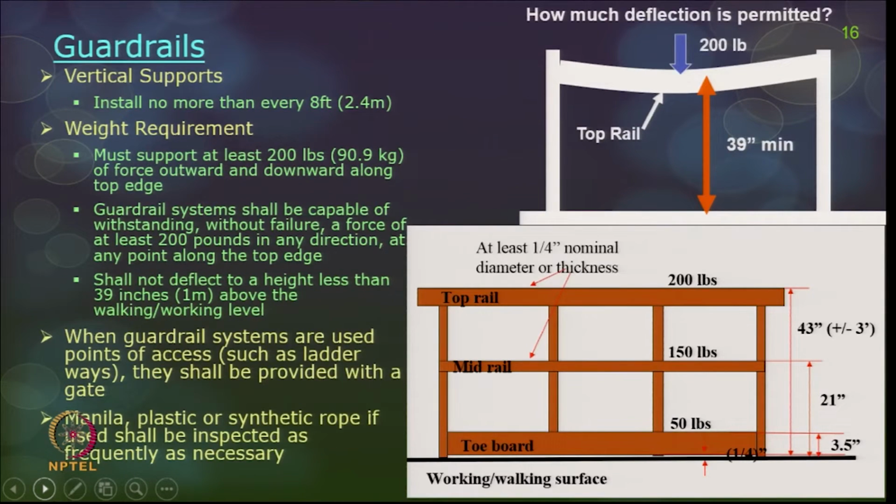So, now the fall protection, as I told, for any opening or any unprotected edges or sides or for a slope roof is primarily called guardrails. Okay. So, what is this guardrail? This guardrail is primarily nothing but a 3-line member, 3 horizontal lines. The top line is primarily called top rail, then we have mid rail and the toe board, and with adequate vertical planks along the support, so that these 3 rails are in position.